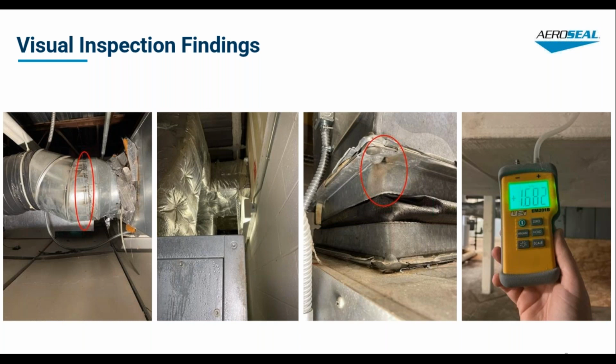It's just kind of pressing out from the pins that hold the insulation onto the ductwork itself. So that's a good example of inflated ductwork. And then another connection that has no duct seal coming right off of the unit, right above the canvas. Lots of leakage there. And then one of the static pressures that we take off the air handling unit.